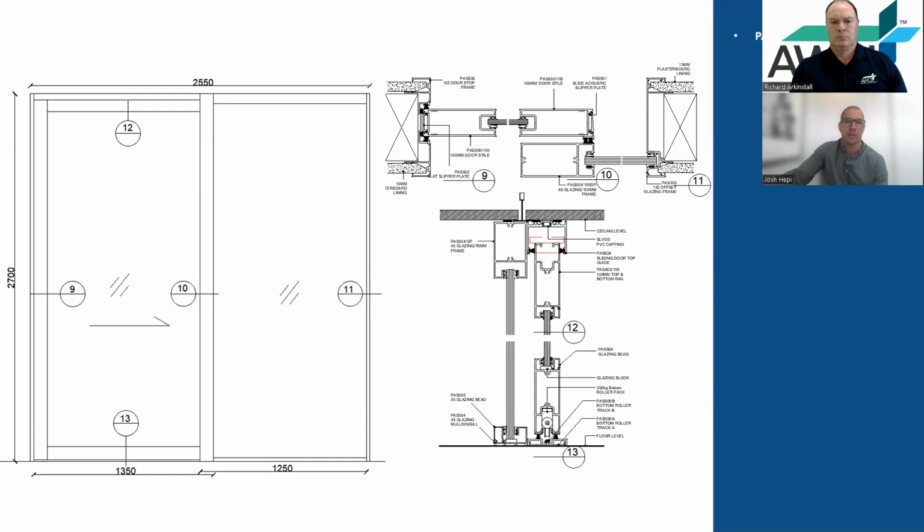we're going to have a door receiver as per this detail, which is the PS 535. We need half a length of 332, half a length of glazing post. Then that's our vertical parts done. In this case, on the ground is the C series glazing sill. So we're going to have 1/4 length of 004, 1/4 length of bead to go with it. This has been designed with a 75mm post at the head here, so we're going to do 1/4 length, which just goes across the top here.